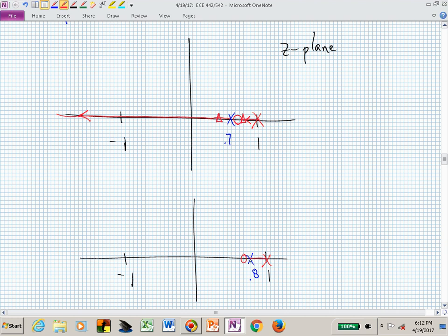You have these 2 poles coming together. They break away at the geometric mean defined by the 0 and the pole location. You can calculate that, but it's somewhere here. Then they form a circle, and that radius is not very big. And what happens? One pole goes here, and one pole goes there.